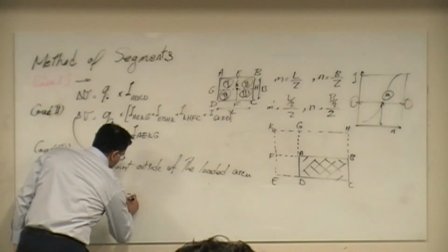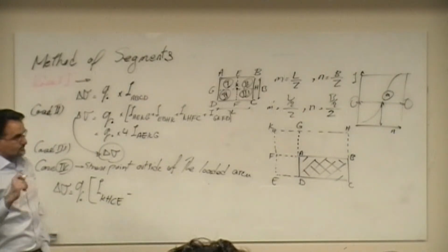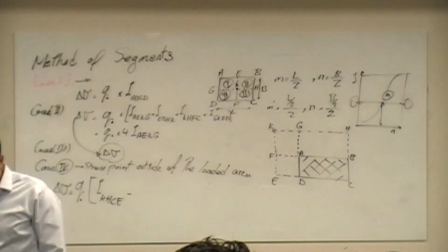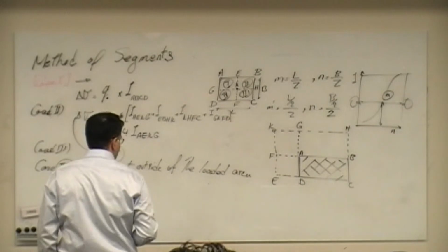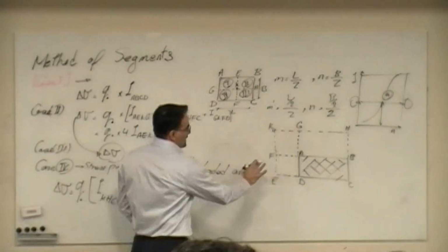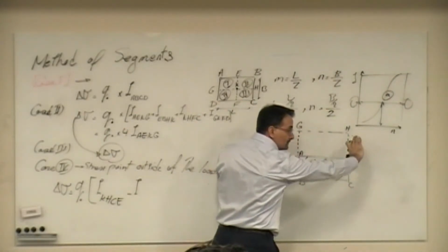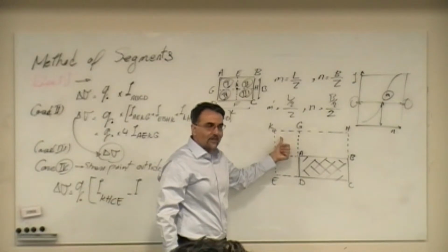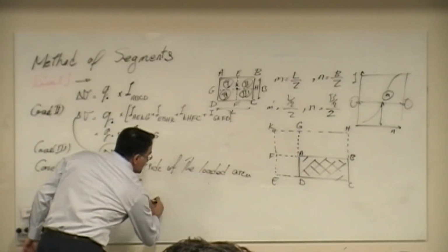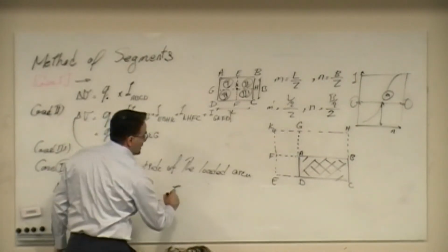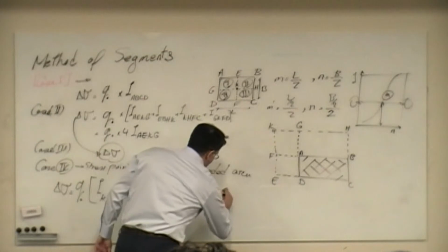All right, so tell me what I have to subtract. Rule number 1 of method of segments: you have to make sure that the K point is always in that rectangle. So let's assume that KGED, I subtract this. The second part, I subtract this. You have to add the other one back in. And since I subtract this part 2 times, I'm going to add this one. It also shares the K point. KGDE minus influence factor of, again, KHBF, plus influence factor for KGA.